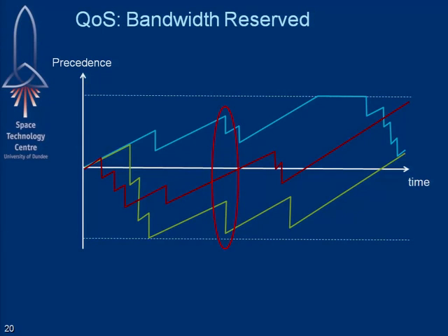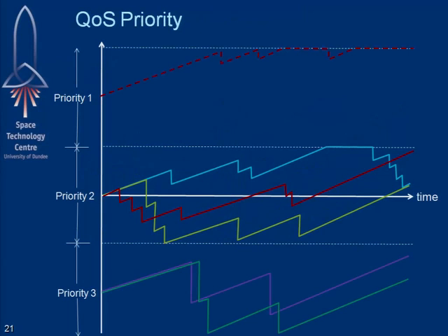So to incorporate priority in this in a consistent way, what we've done is we've added a few extra bits at the top of that counter. Okay, so that gives us some extra range to our counter. But the individual bandwidth reservation counters can only clock up to a certain amount, and then these top bits are set according to priority. So that gives us, in this case, I've shown 3 priority levels. So you can imagine 4 priority levels using, say, 2 bits at the top of the counter. And then we've integrated priority with the bandwidth reservation.